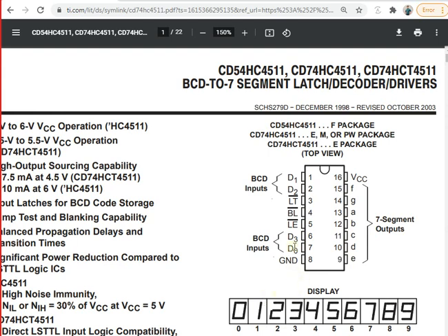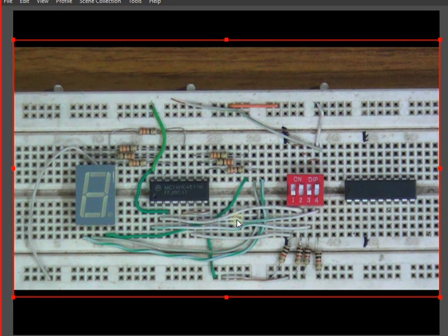So you are giving a binary signal at D0, which is the least significant bit, D1 the next one, D2 the very next, D3 the very next. So you are providing a 4-bit number, you are providing VCC and ground to the IC, that is 5 volts and ground certainly, and then you are going to have F, G, A, B, C, D, E, just like you have done previously. In the experiment you had a 7 segment, so you just have to connect through this F through a resistor, just like I have done over here on this breadboard at present.